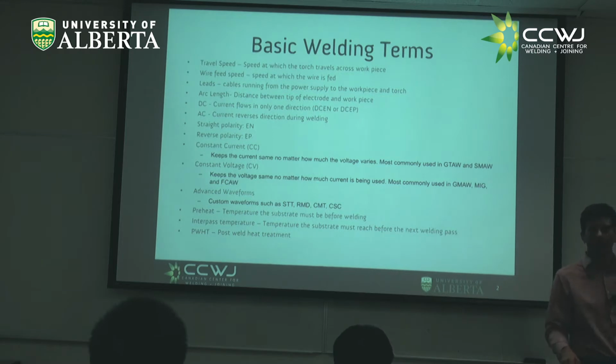You have a lot of chromium in stainless steel, more than 13%. And if you heat it up, the kinetics will be that they combine and make chromium carbide. Now, chromium carbide is super good in many things, but in stainless steels, it's super bad because the carbon now absorbs the chromium and it's not stainless anymore. And in addition, you have a precipitate that makes the toughness horrible, right?